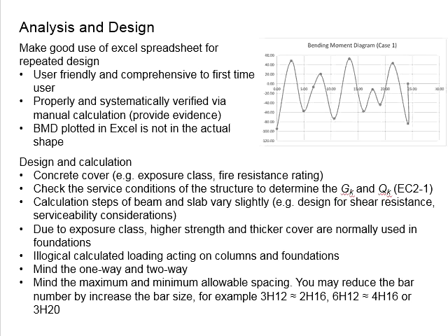This may lead to the so-called systematic error, which is when you use everything similar. Most likely your manual calculations, which were meant for the verifications, are actually replicating what the spreadsheet is doing. Technically, this is not verification. That means you will require at least 2 to 3 different load cases under different conditions, which are not repeated from the one that you used in development of the spreadsheet, to cross-check whether your Excel